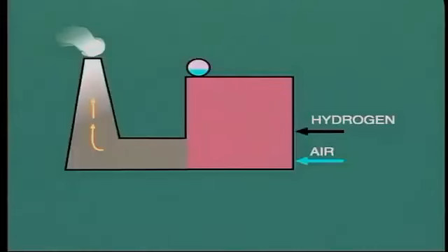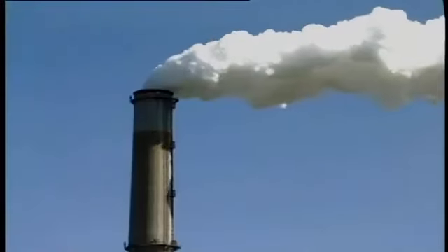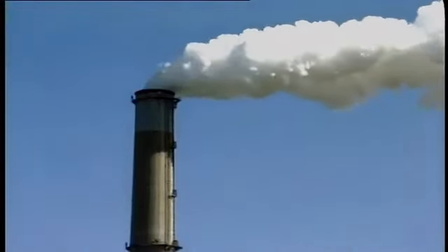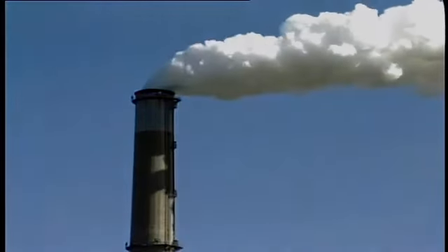in the flue gas. We have already seen that the combustion of hydrogen releases a lot of heat and also produces water vapor. In the example studied, this came to 0.855 pounds of water for each pound of fuel oil burned. As we pointed out, this water is in the form of vapor as it passes on through the boiler and out the chimney to atmosphere.